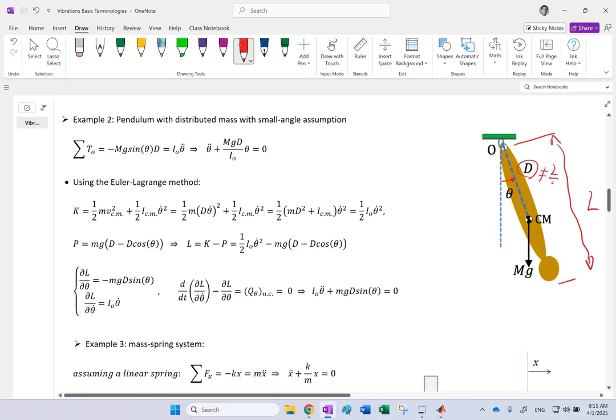And in this case, what is the equation of motion? In this case, still it's the same. Again, if you draw the FBD, you have mg and you have the two pin forces. The pin forces have no moment about O, mg does, and again, remember there is mg sine and mg cosine. This cosine has nothing.